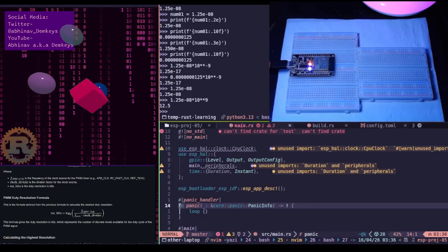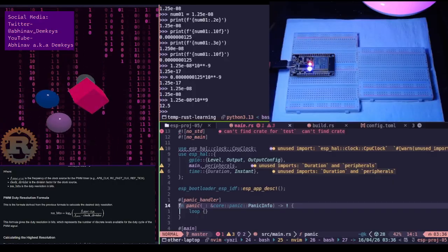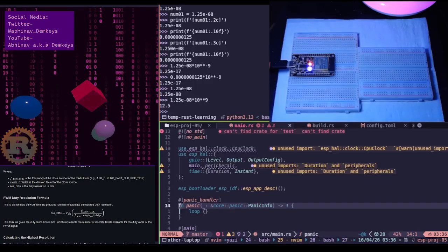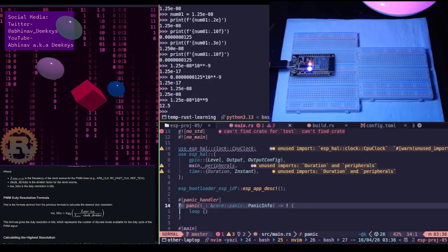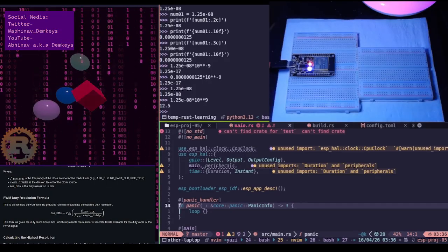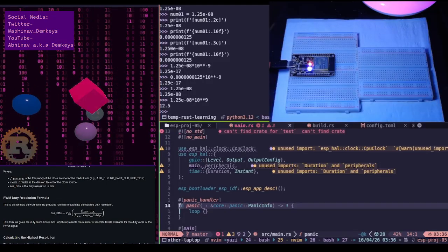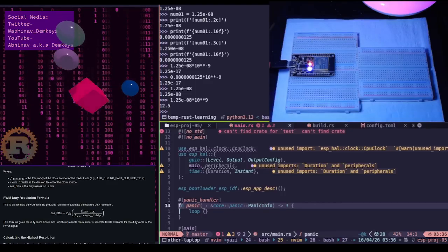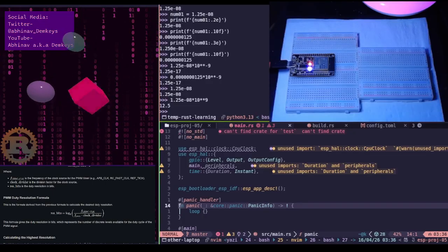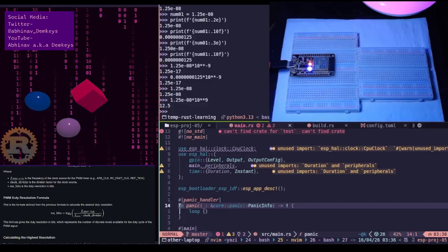There are a bunch of projects that I plan on doing where there will be times where I need to combine circuits, or at the very least join grounds together, and there is a certain level of analog knowledge that I need to have in order to do that properly and safely. A good example would be an ultrasonic atomizer circuit or module, which is a 5-volt module, but it operates at a very different current than the ESP32. And then, of course, we have the ESP32 as well, which